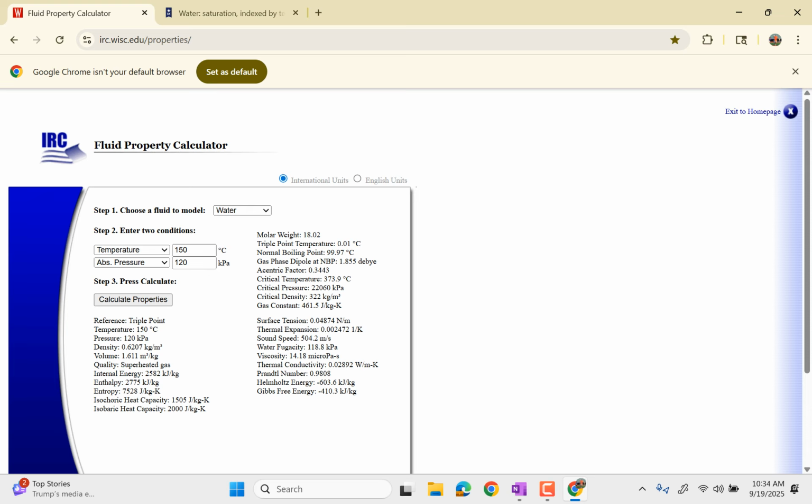That's above the point where all of the water would turn to vapor from liquid. And it has this specific enthalpy, this specific internal energy, and specific entropy there. So you can look up all this stuff for it. Interpolation is just used with tables to get a slightly worse approximation of the same information.